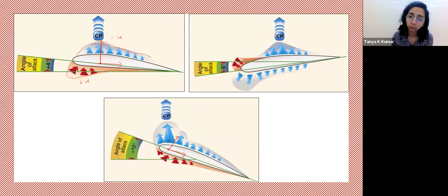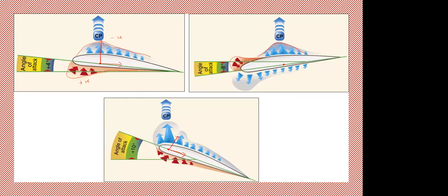Similarly, if it moves downwards, this positive pressure that was below the airfoil surface has now traveled above the airfoil surface. So there is a small quantity that is above the airfoil surface, and the other quantities move backwards. Now the net pressure distribution happens at a point that is towards the trailing edge. It has traveled backwards. Okay. So that is where we represent our aerodynamic forces.